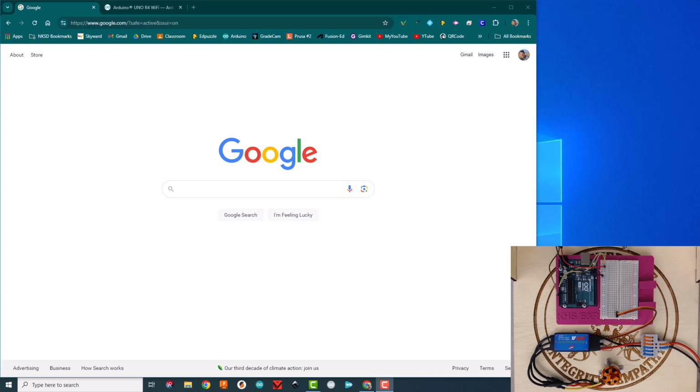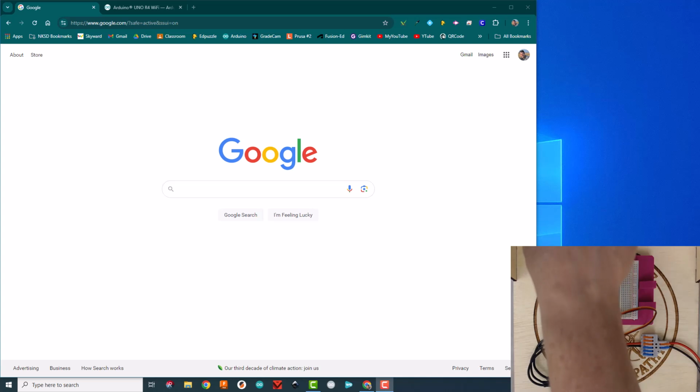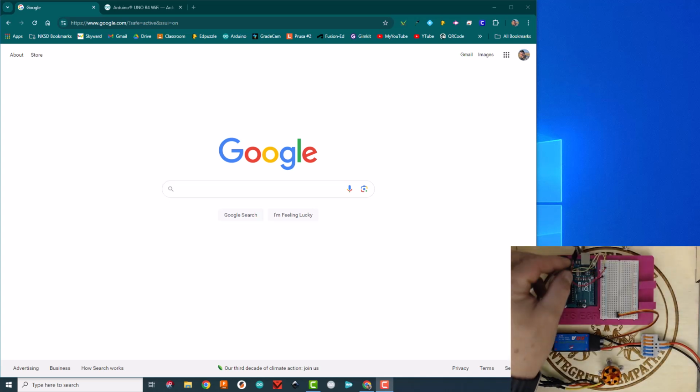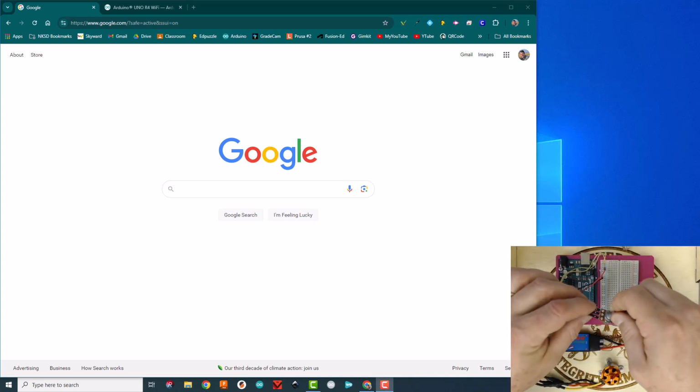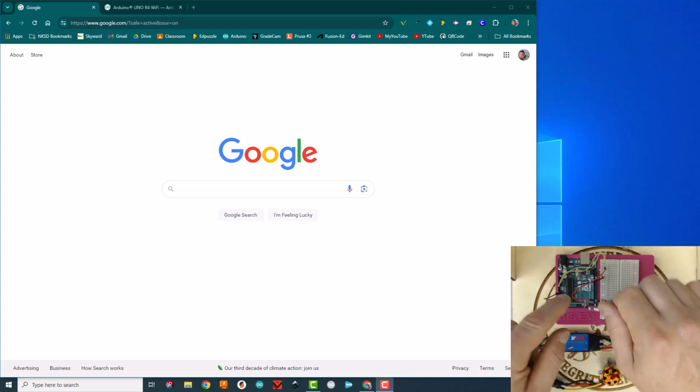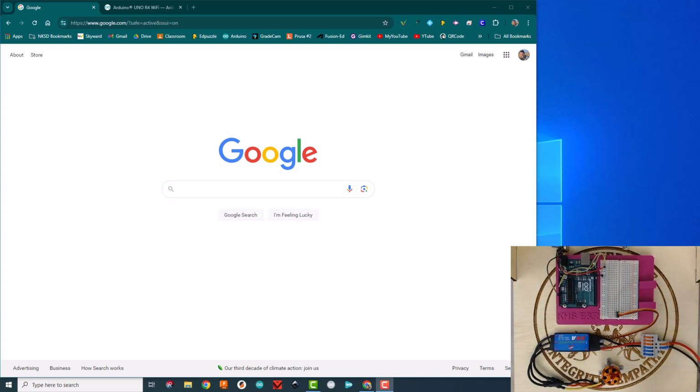Today we're going to be learning how to create a program in Arduino and control our motor using a potentiometer. So the whole process, the overview of it, looks something like this. We're going to read data from our potentiometer here. The turning of the knob will read the voltage change on that middle pin, and we'll use that information to tell the Arduino to send speed commands to the ESC. So that we turn it one way, we go to full blast, turn it the other way, we go to stop. And then we'll see it work on our motor, hopefully.